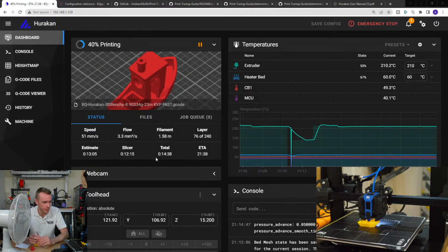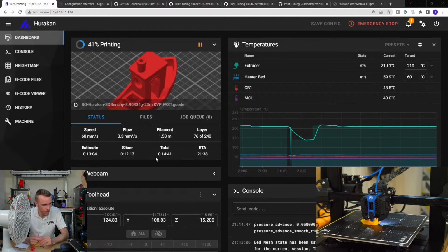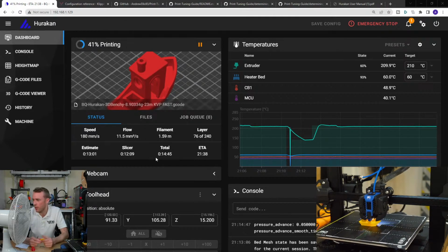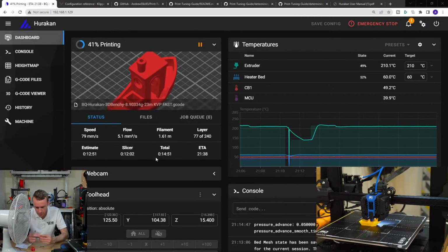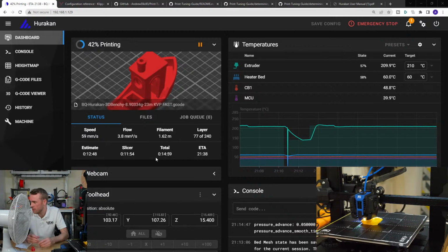You need boatloads of retraction, don't you? I tried 3 before and it was super stringy. I've not done a retraction test. I'm literally just guessing. The B1 profile, which is what this is supposedly based off, suggested, I think, 7mm on the Cura profile. I think that's what we discovered in the last stream.